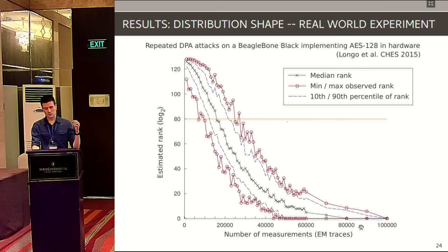So if I wear the hat of an evaluator under what I said was the current way of doing things, the interesting part is down here or here, which is where the attacker starts winning perfectly. On average, this is around 80,000 traces. But the adversary starts getting a luckily perfect attack at around 50,000 traces. And in fact, this is what my colleague Jake reported in his paper.